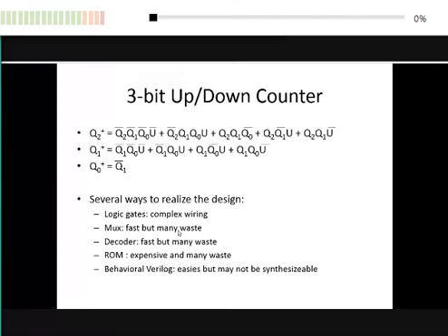For ROM, of course, there are more ways. Okay, because you want to do storage there, so it's not feasible actually. But there are a few cases people do it. For example, in a lookup table, if your finite state machine is being used to generate a lookup table output, actually it's faster to build using ROM.